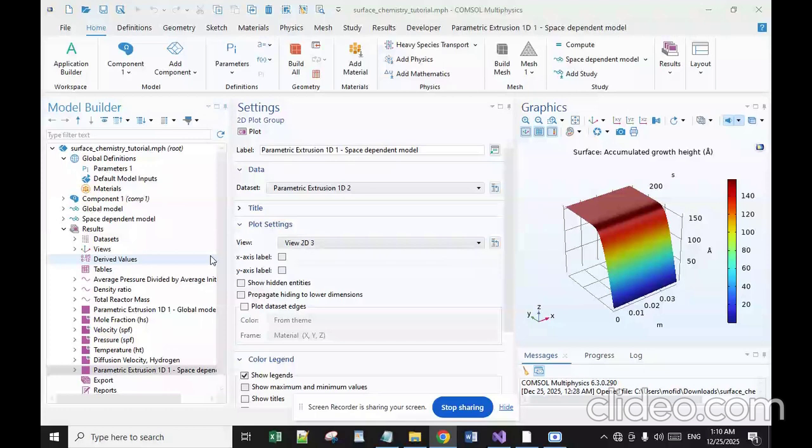The net result of these two competing reactions is SiH4 gives Si(b) plus 2 H2, which means that it is expected that the silane is replaced by hydrogen inside the reactor and layers of silicon are deposited on the wafer surface. Global model equations.